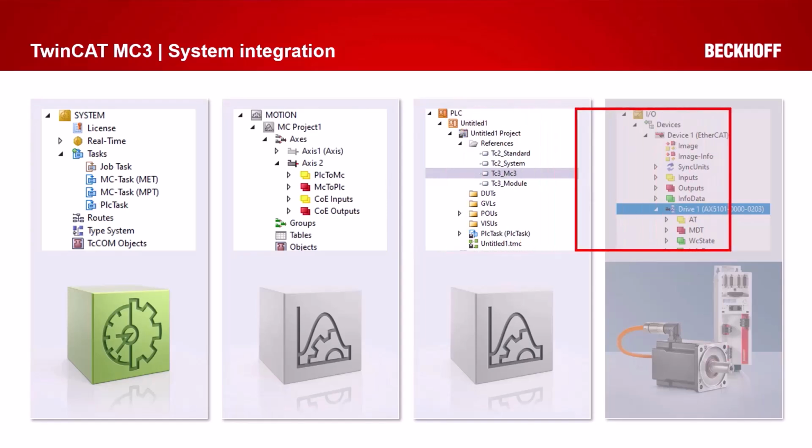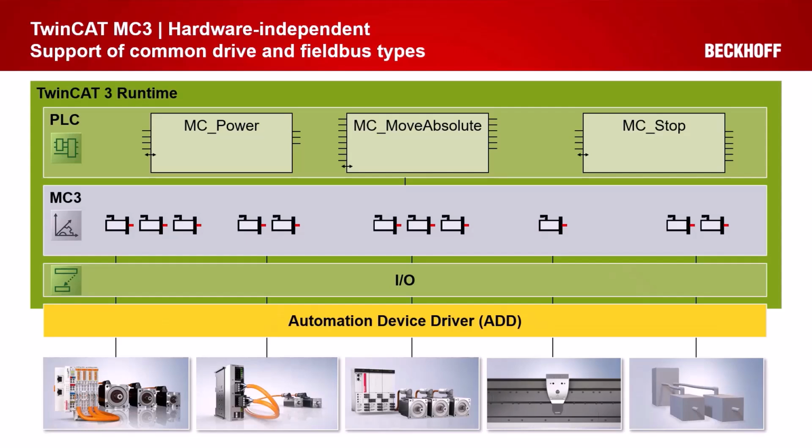Nothing changes on the I/O side. The drives stay the same. Abstraction is still a core concept. So your PLC coding that you develop, the axis type that you are controlling, whether it's a hydraulic axis, is now all incorporated into one environment, and then EtherCAT going out to the drive allows you the abstraction aspect.